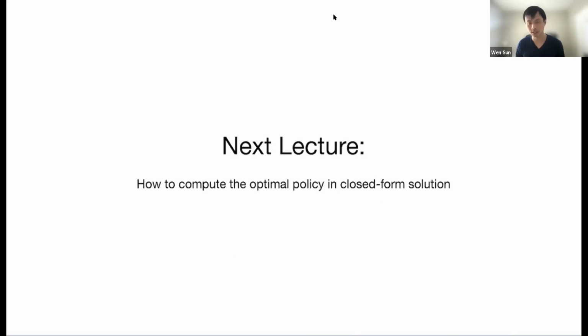So we introduced this LQR model, and it's a very simple model. You can argue that this is a very naive model, because there are not that many things in the world that are globally linear. But this is a nice model. It is a nice starting point for us to start optimal control, because this allows us to compute the optimal control policy in closed form. As you already saw, the optimal policy will be linear in state, and the optimal value function will be quadratic. And we can write out the closed form solution.